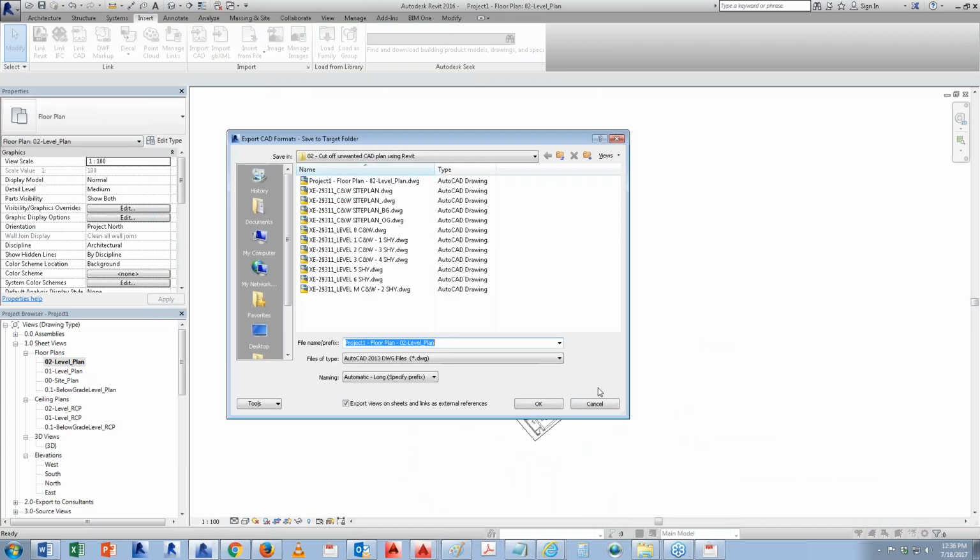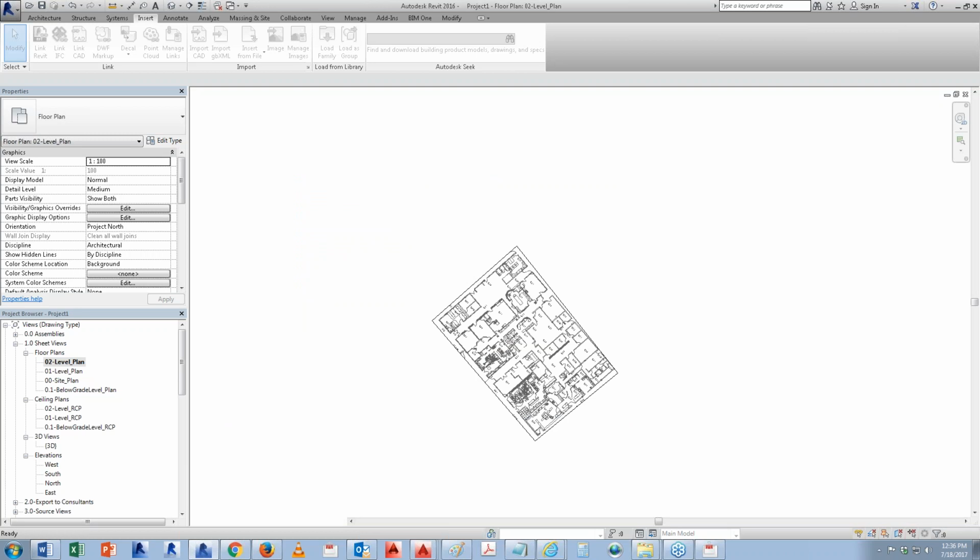I mean, this is just a technique that I show people, saying that if you guys want to cut it off, then not just use delete, because I know that people just use AutoCAD and just say delete. That takes you forever. Imagine you have like 20 floors of the same version. Now the nice thing about Revit is that you can actually transfer this clipping into the multiple levels as well. So what you're doing is that you're getting a consistency.